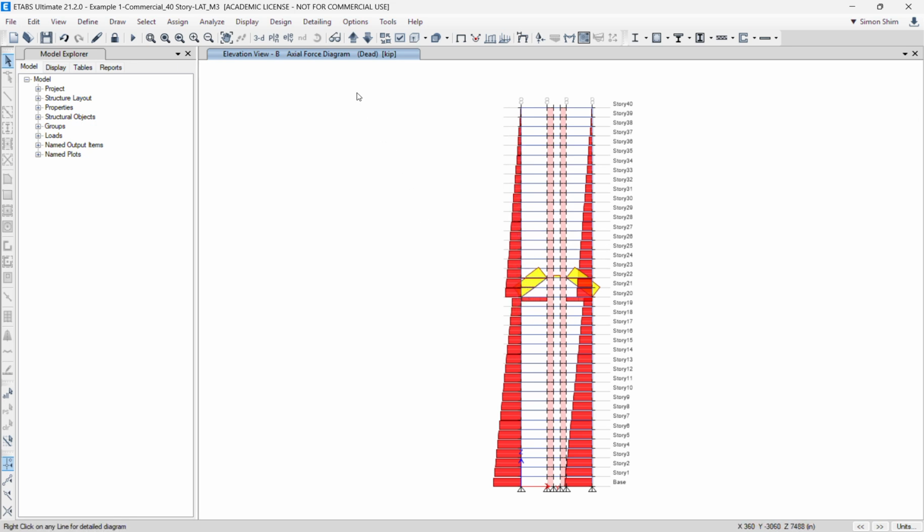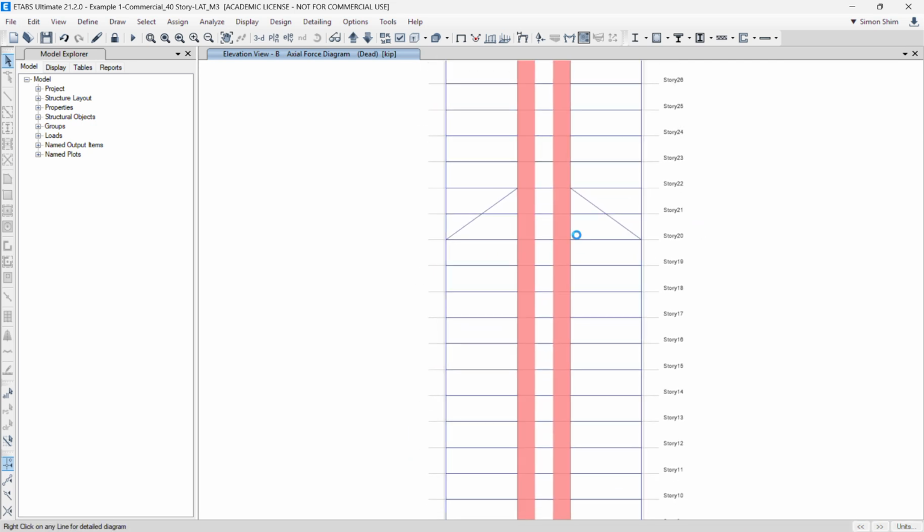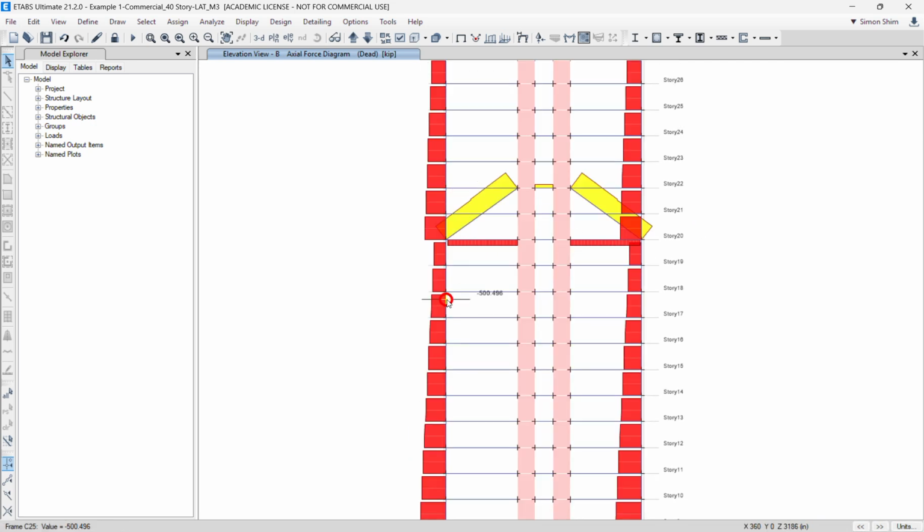The current model is just the complete model. The building was constructed and all the design loads, especially gravity loads, are assigned at the same time, which creates this situation. The column actual load is coming down, right? But the column reaction is reduced. The reason is that the bracing members are holding it up. So this is not a good condition.